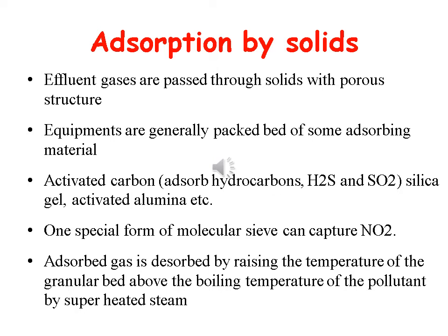The effluent gases are passed through the solid, and the equipment consists of a packed bed of adsorbent material. The commonly used adsorbent materials are activated carbon, activated alumina, silica gel, molecular sieves, etc. In that way we attract and collect the gas pollutants into this adsorbent bed.